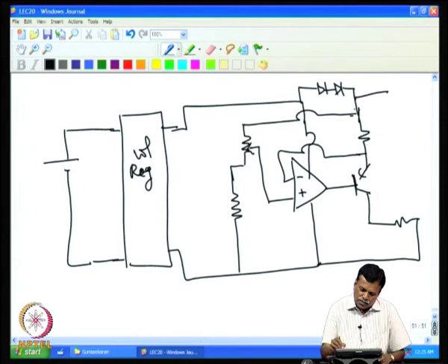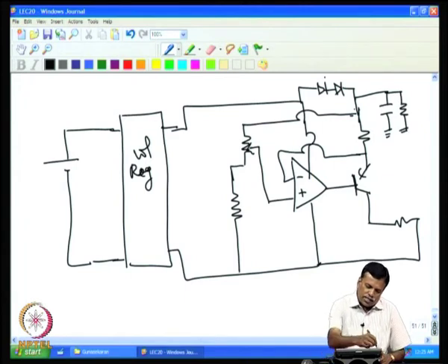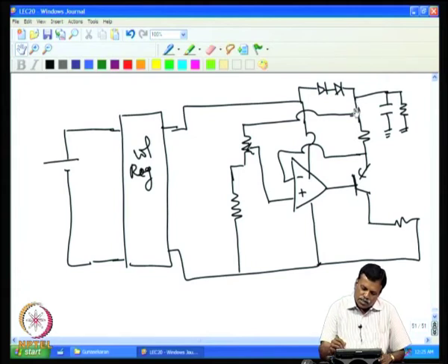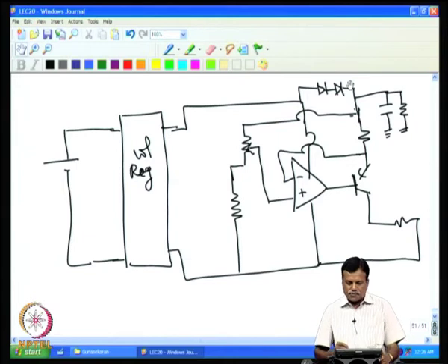Then to make this point stable we can have one capacitor, and a very small current can go in this to make sure that the diodes are biased and some 1.2 volt drop is there. So, now 1.2 volt reduction in voltage is achieved by this arrangement. So, the earlier issue of the inputs going up to the supply voltage terminal is resolved by adding these two diodes.